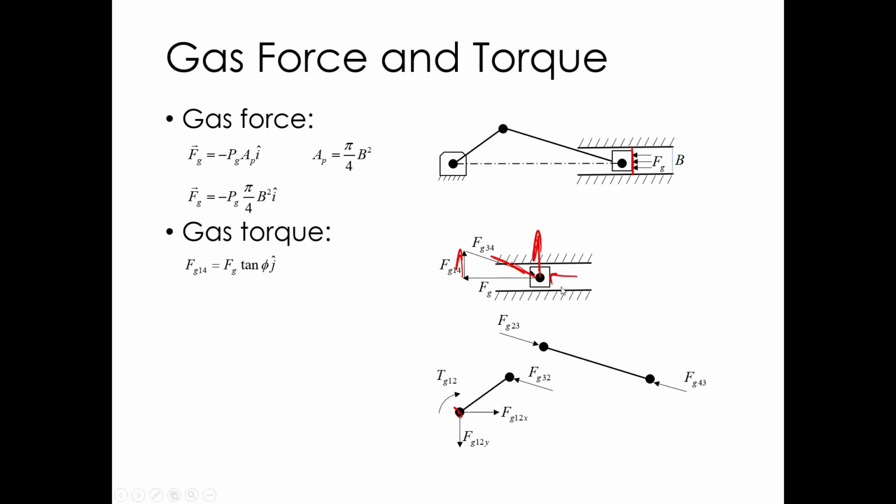So some of this pressure here, because the connecting rod's usually at an angle, is going to result in some kind of side loading on the wall of the cylinder. That side loading on the wall of the cylinder, about the crankshaft center line, is going to give us torque. It's going to try to rotate the block. So this force here is just going to be the gas force times tangent phi. That's 1 on 4, and 3/4 comes from just this little vector triangle here.